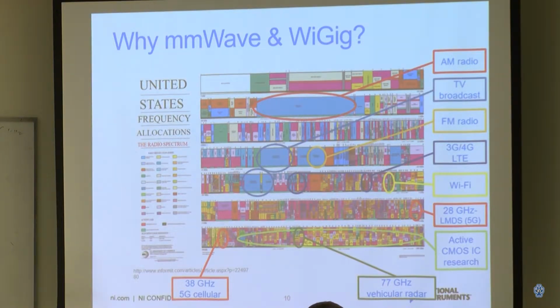And since there is more and more technology development, we need to find some frequency ranges we can use, and there is still some unlicensed frequency band. If you zoom in, it's here. There's an area over here with 60 GHz unlicensed. It has been used for WiGig, like the 802.11 family of signals. What WiGig means, I will go through later on. It basically has a really wide instantaneous bandwidth for data acquisition and video streaming. It will make things way faster.